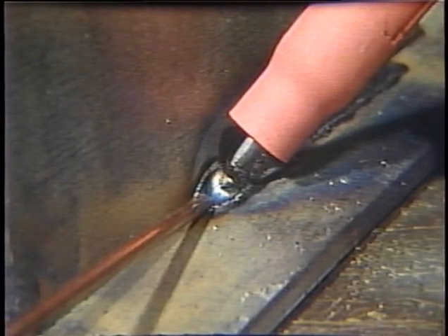Another form of entrapment discontinuity is the metallic or tungsten inclusion. These are electrode particles trapped in the weld deposit and come from the electrodes used in gas tungsten arc or plasma arc welding. Tungsten can appear in a weld one of two ways, either scattered in fine particles or in one large particle, as in the case when the electrode tip is broken off in the puddle.